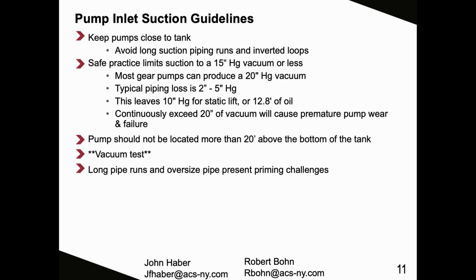This slide is in reference to pump inlet suction guidelines. Getting the oil into the pump is the hard part. The positive displacement pumps will positively pump the oil to the destination. Best practice is to keep the pumps as close to the tank as possible. Try to avoid excessive suction lengths and inversions. Suction pipe sizing is critical when sizing.